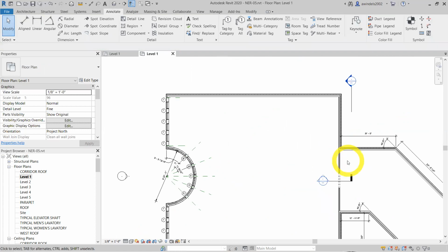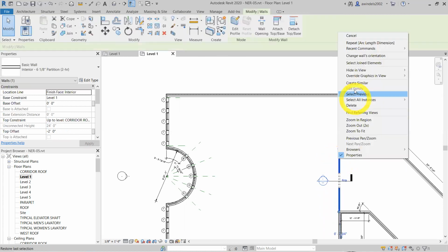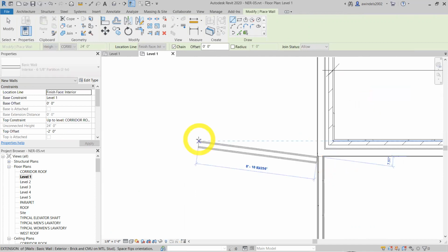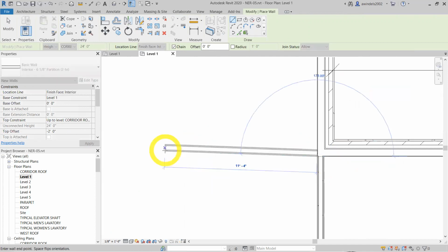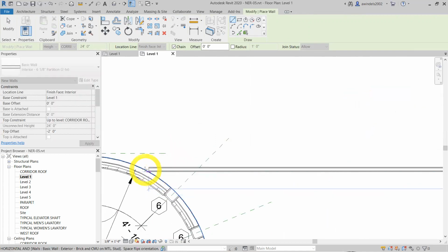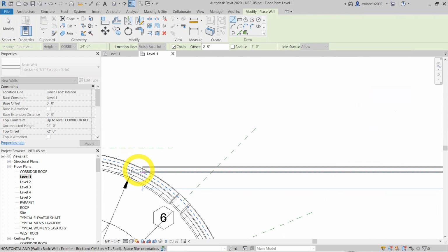So I'm going to pick the 6 1/8 partition wall. I'm going to say in this case, create similar. I'm going to start right here, like the zoomed in picture on the bottom of 243 does. And I'm going to flip it since it's symmetrical. We'll go straight to the left, the east, excuse me, the west in this case, right about here to the center.